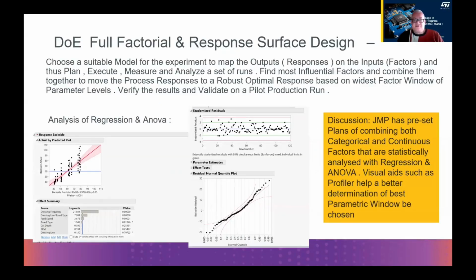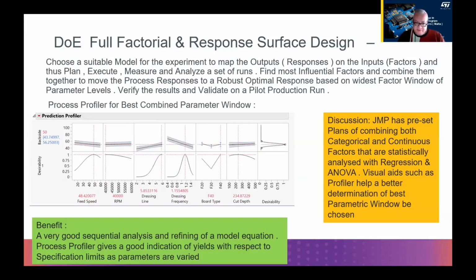So basically, you can see here that you got all the tools that one needs for statistical analysis of the design of experiment. From it, later on, we see the profiler. We can do also process space, where we see how variance in our inputs will affect the output. Here's the profiler. We're gonna optimize at a particular level. There are some tricks also that you have to understand that, for example, if you are reducing a particular response, it must not go down completely to minimize, but target a lower level. And you can see that you can have the optimal parameters for each factor, whether they are stable, whether they're robust, whether they are affecting much, whether they're not affecting much.